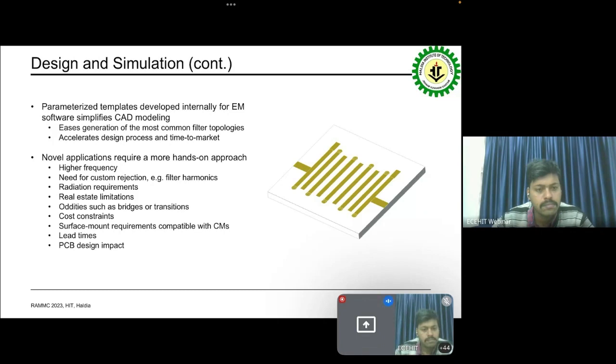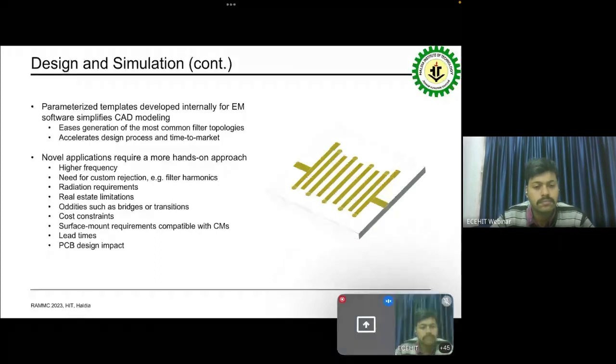EM Pro, for example, will tie back into ADS, and you can actually take those EM models that you've developed in EM Pro, bring them over into ADS, and run a lot of those optimization algorithms on them. And there's been a lot of advancements with those black box, computationally expensive optimization algorithms. That's the formal term for it. Just beyond the simulated annealing optimization algorithms, there's been several new ones that have come out. I think recently I saw one come out of Berkeley that uses radial basis functions to perform those optimizations. And I again went into Python, put together a software plugin for that to bring that over into my EM modeling setup, and it performs exceptionally well. You can get away very often with 15 or 20 iterations as opposed to several hundred possibly with other algorithms. So mathematicians, computer scientists, and engineers, there's a lot of development effort into those optimization algorithms because they are critical.